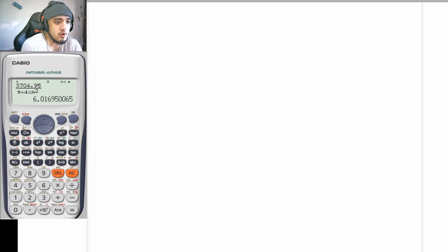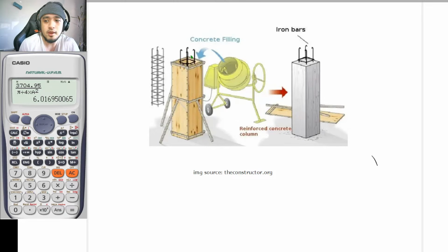However, guys, during concrete pouring, if we would be once again pouring the concrete to our formworks, if we do not have our lateral ties, during concrete pouring, our steel rebars might be misaligned. So that is the use of our lateral ties. But once again, theoretically speaking, if we are only to have concentric loads here, these lateral ties are not really needed because we do not have any shear.